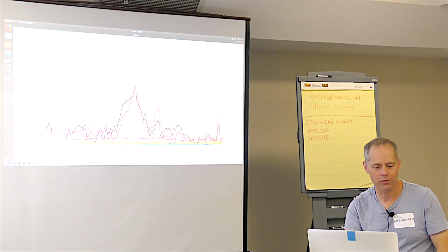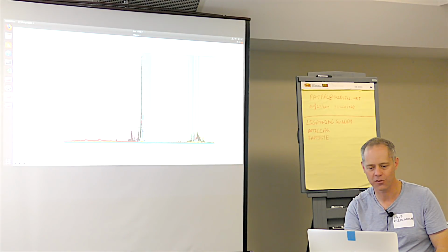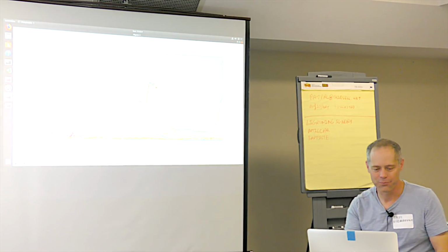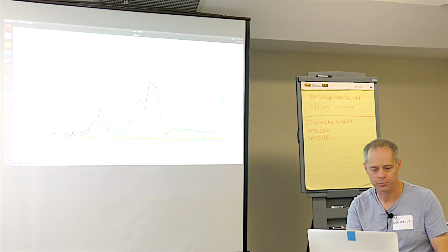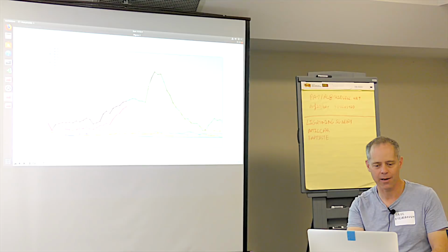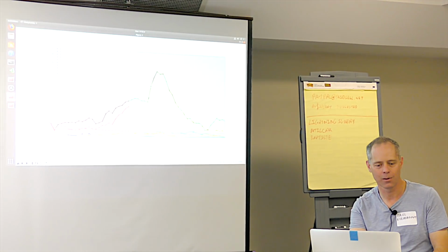So now we zoom out and we go, well, okay, this wasn't the bit that scared the operator. The bit that really freaked the operator out was this part here, because you can see it went into RTL. So let's have a look at what happens here. We have another divergence. It started to diverge here, and now it's gone into RTL.